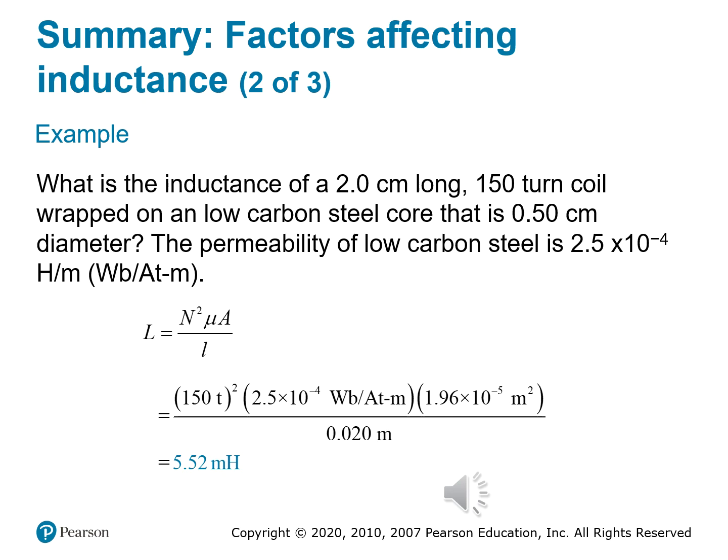So let's plug those numbers in. L is equal to 150 squared times 2.5 times 10 to the negative fourth times 1.96 times 10 to the negative fifth, all of that divided by 0.02. We end up with an inductance of 5.52 millihenries. And what does this tell us? It's a number, but what does it mean?